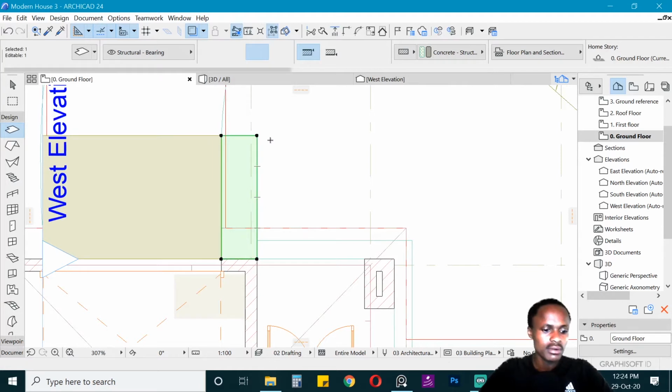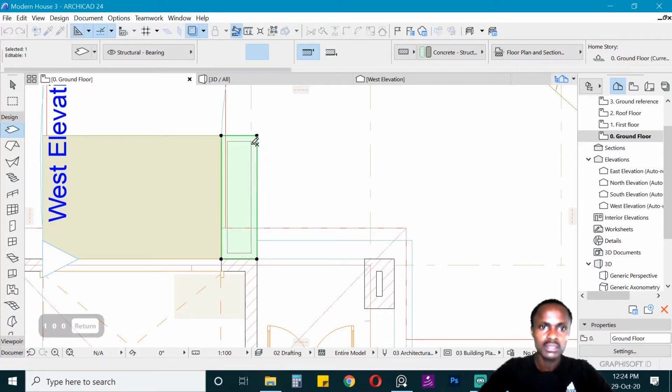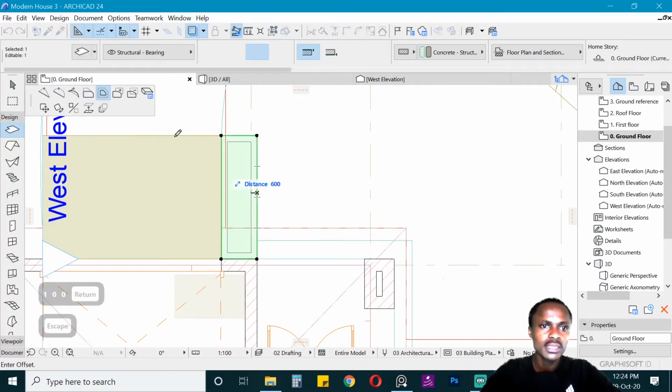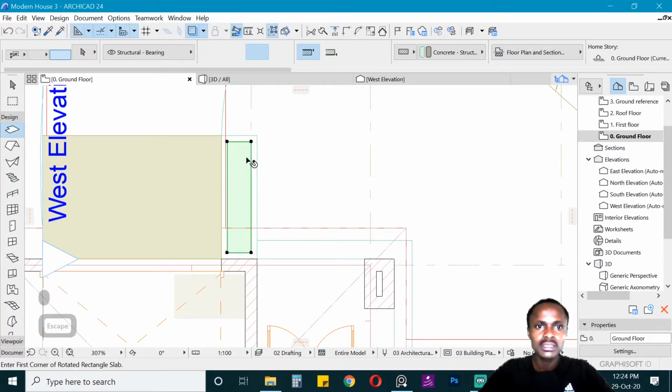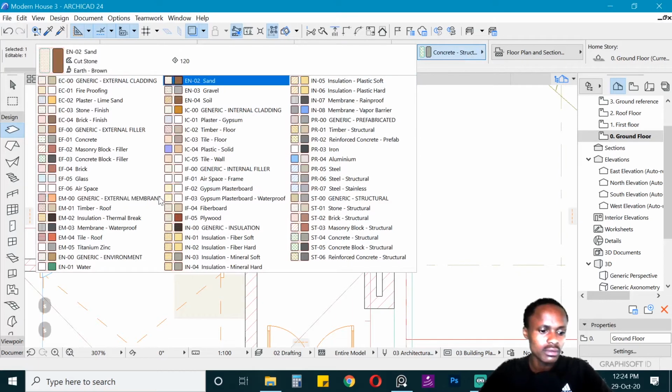Once you're happy there, we can make a copy of this, give it a thickness, maybe what a wall would be like 100. Just subtract this inner portion, and maybe this inner thing should be smaller, so I've picked the one which is negative 150, and maybe it should also be soil as opposed to concrete, because you want to put plants in there.